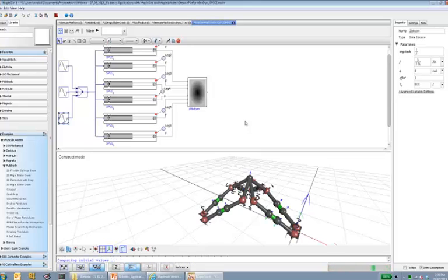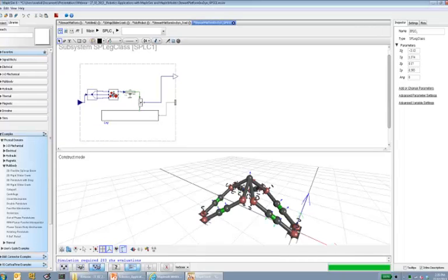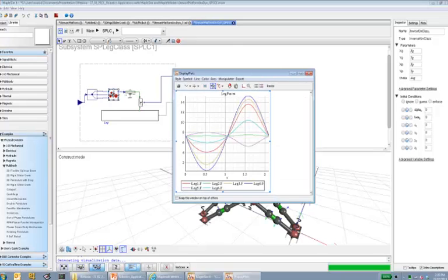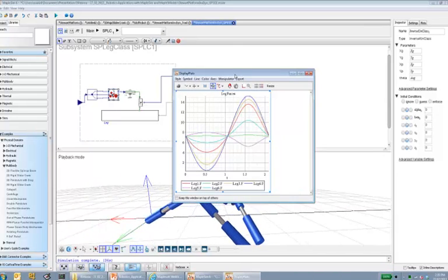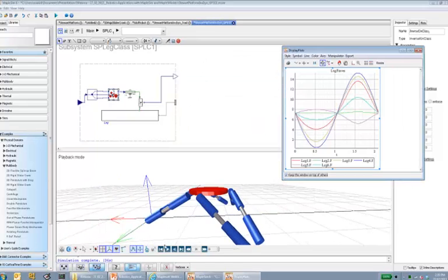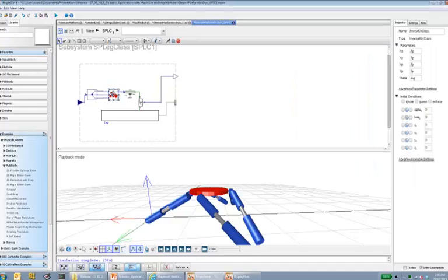So the idea for this particular model is that we are providing the desired position of the platform to each leg, and each leg is extended according to the inverse kinematic solution of the Stewart platform, and we end up with the correct or desired position of the platform itself. So how can we do that? We create a block that incorporates the inverse kinematic equations. And this block is shown here.